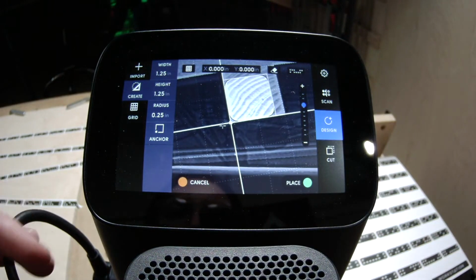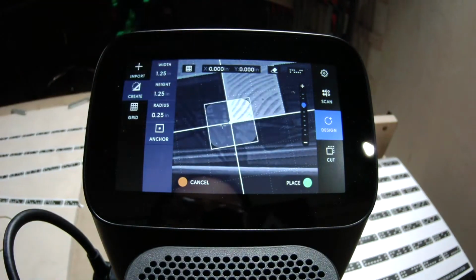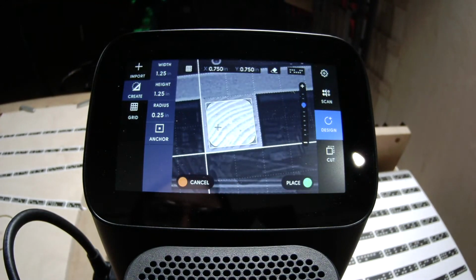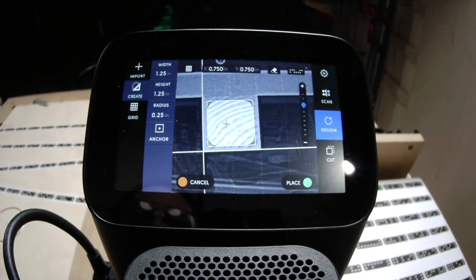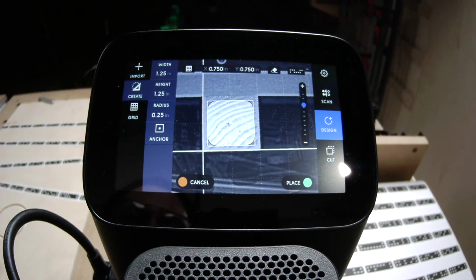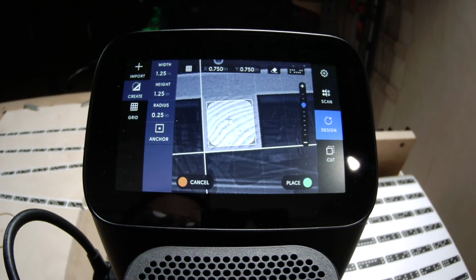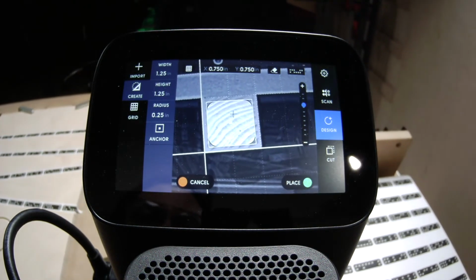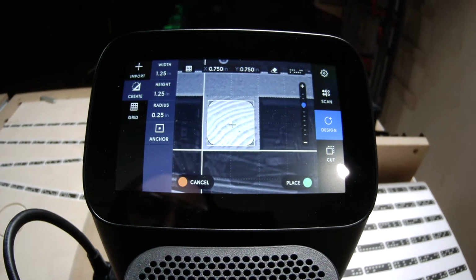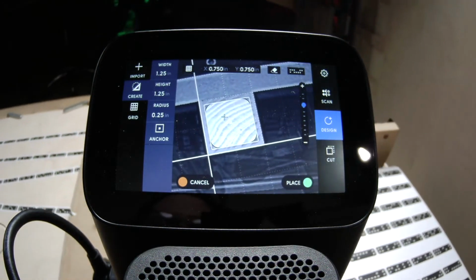And then the last thing that's important here is the anchor point. We're going to place it on center. So I've got now this square that's the size of my tenon. And you can see it's placing right on the top of the material. Now, as I move origin around, that thing's staying stuck right in the center. And that's the power of setting the grid up so you have a center point like that.